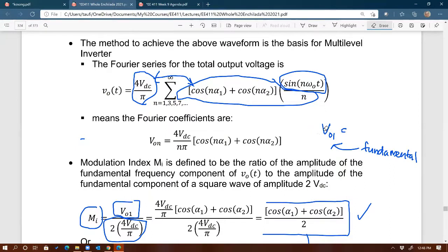In addition to giving us the criterion for targeting the RMS of the output voltage, by using the same equation, I could also lock onto a certain harmonic, where n is the harmonic number, and get rid of it. If this equation is equal to 0 for that particular n, that means I'm getting rid of that harmonic component n.